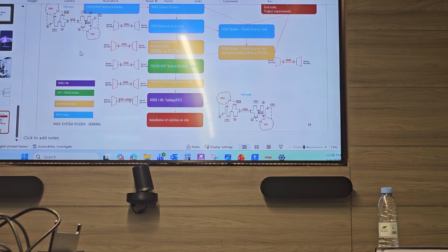Then you step energize the transformer, then energize the cable, and once the voltage is brought to the inverter of the wind turbine, it will see the voltage is there, 60 hertz, low voltage maybe 400 volts or something, and will synchronize and start. Once it's synchronized, it will start rotating and generating, pushing energy into the network.